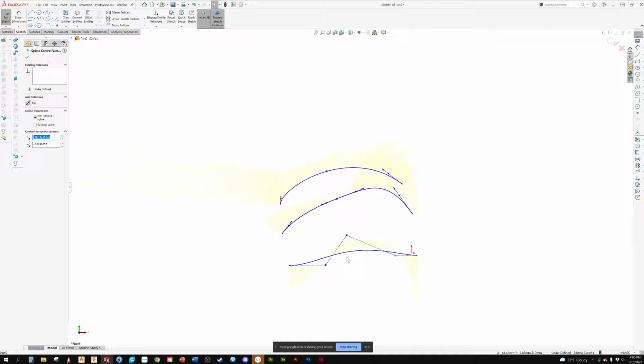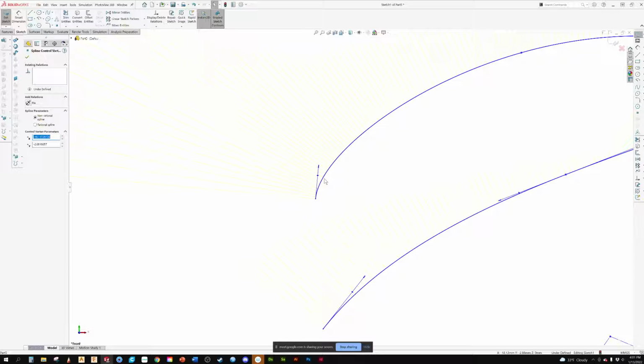That's my knowledge of using the splines. Now, we've talked about when you're drawing the spline, having C1. So C0 is it just touches. C1 is that two lines are tangent. C2 is that they're tangent and have curvature to each other. So here, we've got tangent, curvature control.